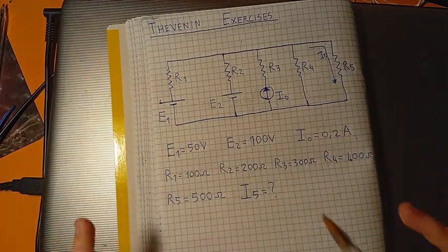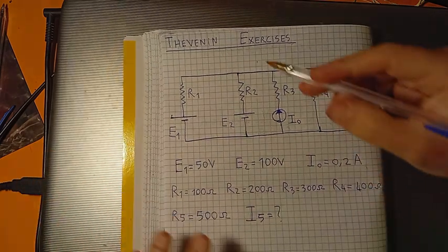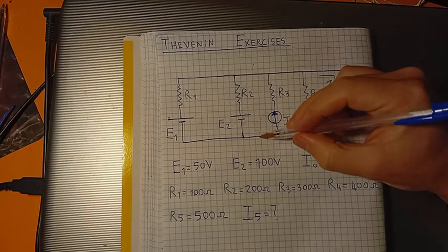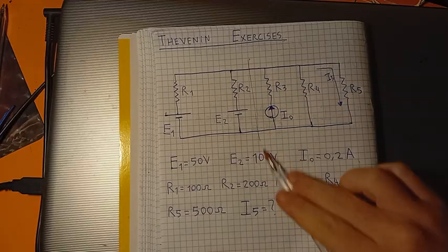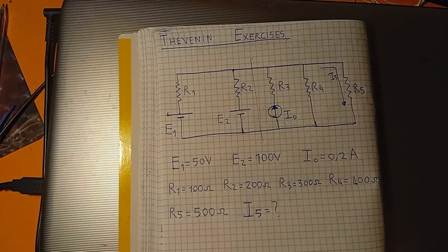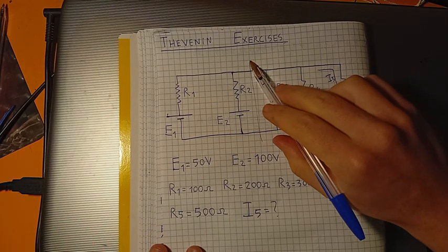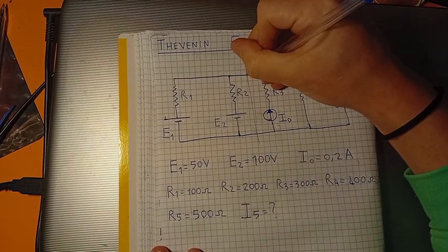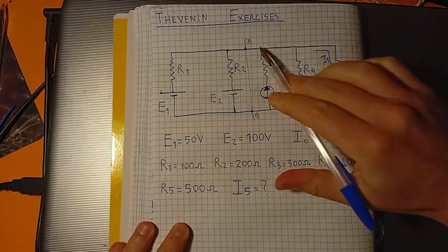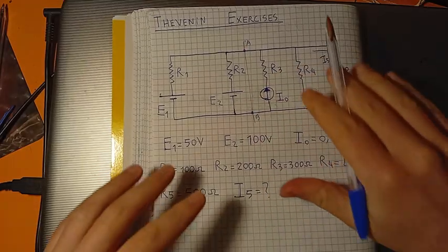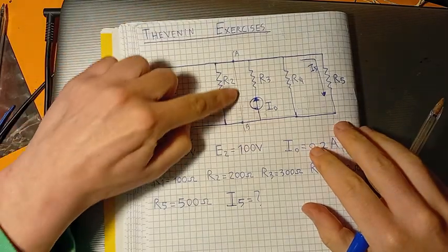Let's begin to simplify this circuit using Thevenin theorem. So the first thing I want to do here is cut off these circuits at these points 1 and 2. So I'll cut off these 2 wires. Remember, you can cut off just 2 wires, okay? No more, not less. So we'll cut off the circuit in these 2 points, A and B, okay. So we have cut off the circuit here, and let's take this part and just put it aside. We are interested now in this other part.